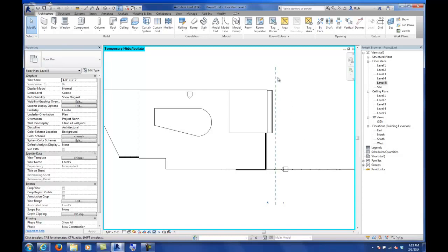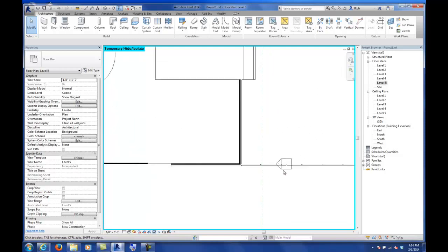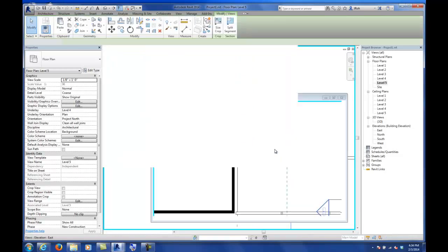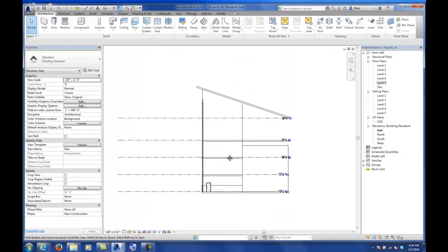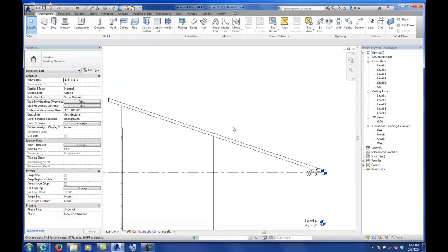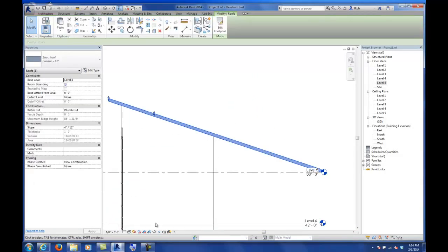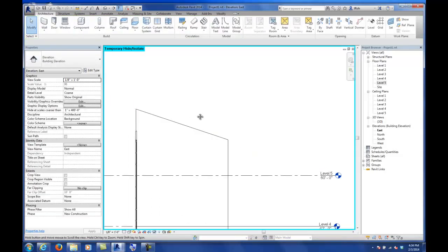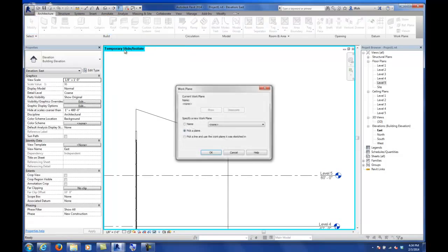Sort of. It's okay. So to do this little section design, all we need to do is look at this in elevation first. So I need to look at my elevation tab over here. I got this little tag. It should be our east elevation. And while I'm in that elevation, I'm also going to hide this other roof because, again, we're trying to draw something different. I'm going to use the roof, so click on the down arrow and the roof by extrusion. Here it wants you to pick a reference plane.